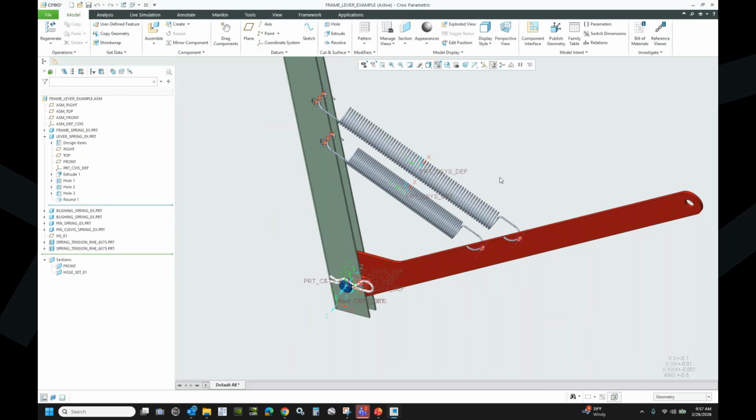What concerns about the performance of a large assembly should we be aware of for flexible components? If we model a rivet and make thousands of them flexible, what happens? Well, that is going to cause some assembly performance issues, right? Because it does have to regenerate each one of those versions. Now, if you do it 1,000 times and they have 1,000 different versions, then you might want to take a different approach. But you could also use a simplified representation to omit those kinds of things